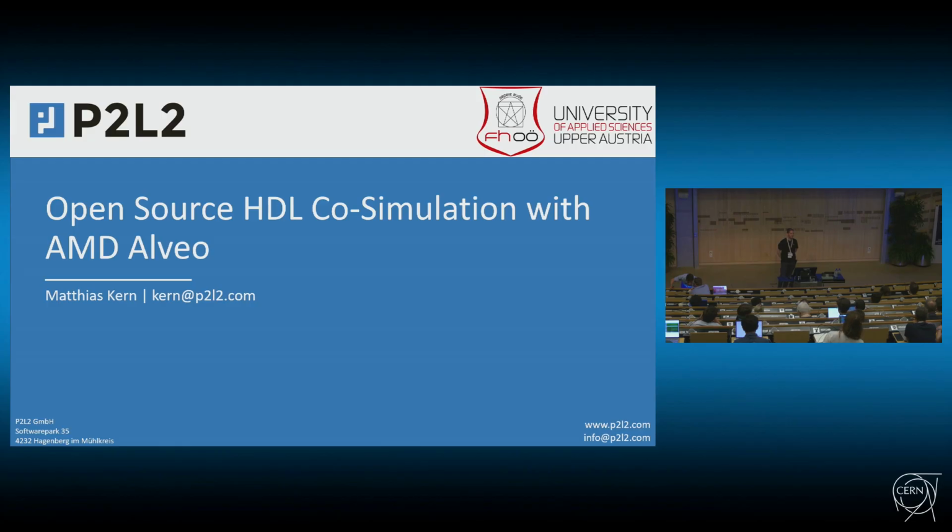Yeah, that's true. But the design is not directly put into the FPGA accelerator, there's logic around it. And you then have the design being reset like it would have been in the simulation. So you start from the beginning because you transmit the reset also to the offloaded part.